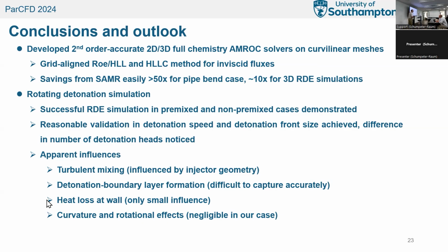We have demonstrated that because all the energy is in the combustion itself, you can cool these engines as you wish, and still you get effectively the same phenomena. We have demonstrated that in other publications. And of course, there are curvature effects, which depend on the annular slit size versus the radius of the engine, but it wouldn't be a loss in the engine that I have shown you.